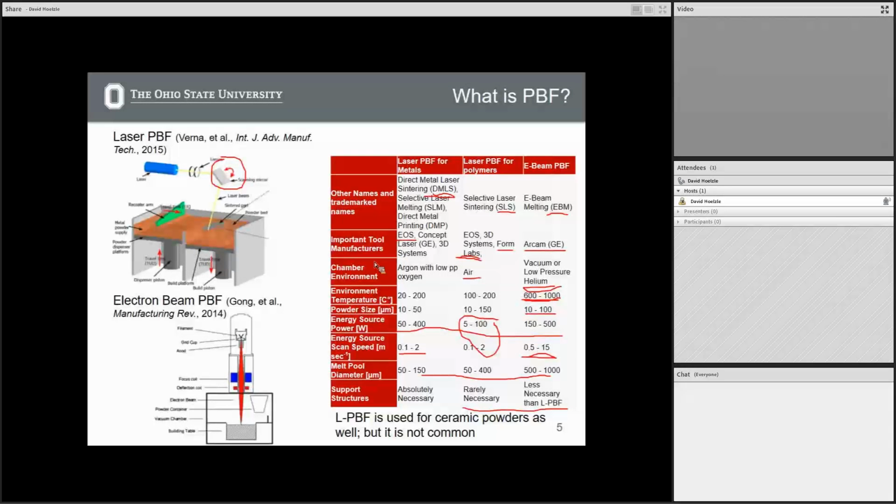Okay, so this is revisiting a slide we went through on Tuesday. I just wanted to go back to this before we start going forward again, because it talked a little bit about some of the features I think will show up nicely in the videos we're about to see. And just a reminder, some ideas about the temperatures that we're operating at. So, laser powder bed fusion for metals. The background, the environmental temperature, is on the order of somewhere around 20 degrees Celsius, which is essentially room temperature in a cold room, right?